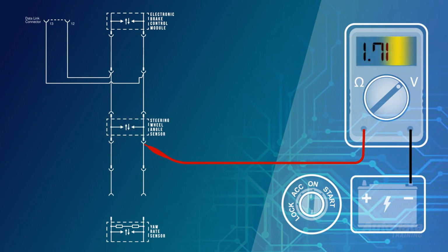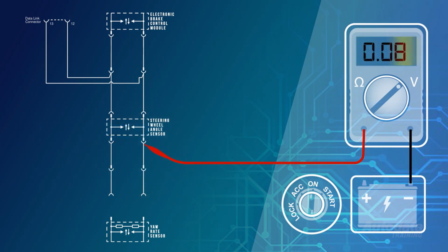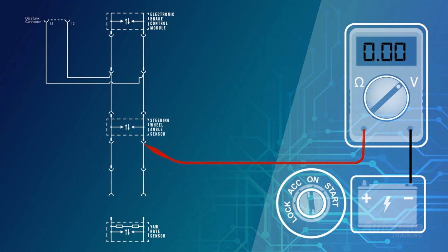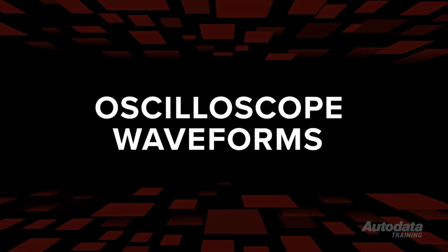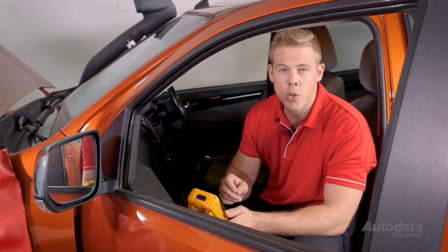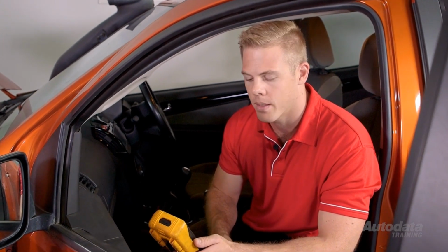If the correct voltage was seen, this confirms an open or excess resistance between the sensor and the inline harness connector. Although, if the meter still displayed low to 0 volts, turn the ignition off and disconnect the SAS harness connector. Inspect for terminal tension and corrosion. Provided our initial circuit testing is correct, this is the only place the fault could be.